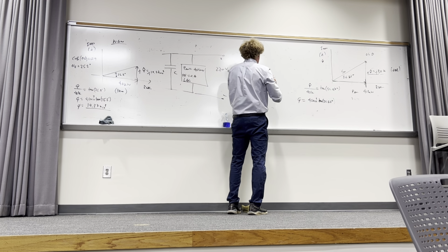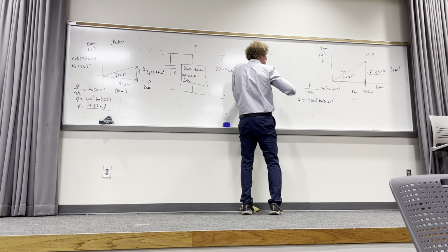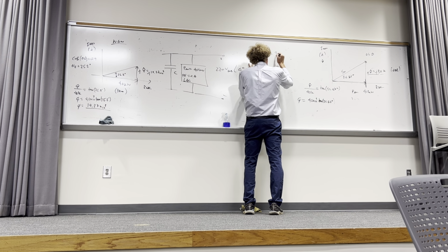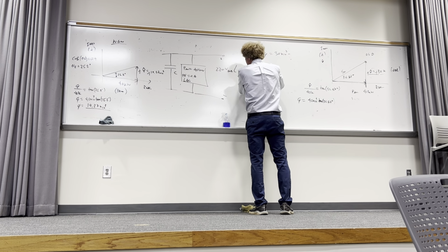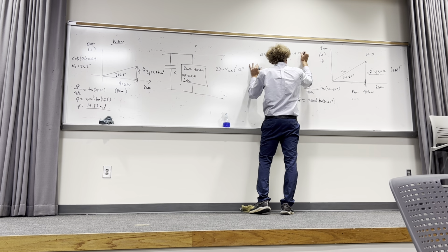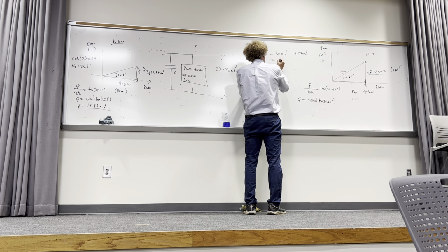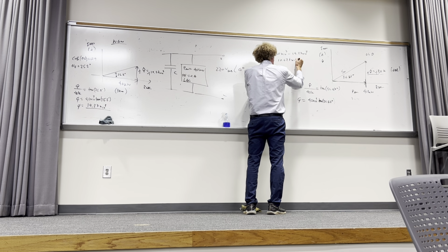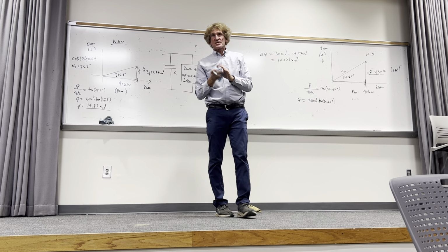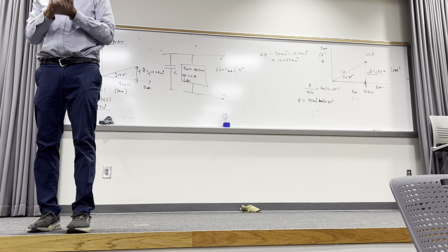So here, for lack of a better term, the delta Q, the change in the reactive power, is going to be 30 times 10 to the third minus 19.37 times 10 to the third, which is 10.627 times 10 to the third, right? You'll notice that's the magnitude. I know it's going to be something that's going to reduce it. You all with me, class?